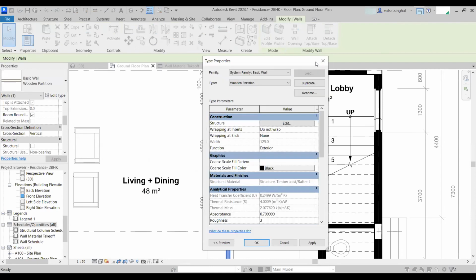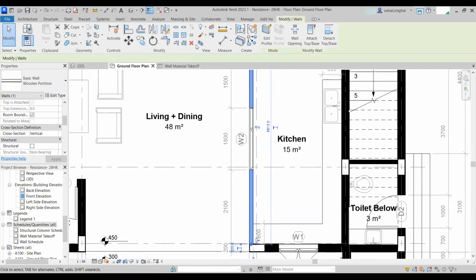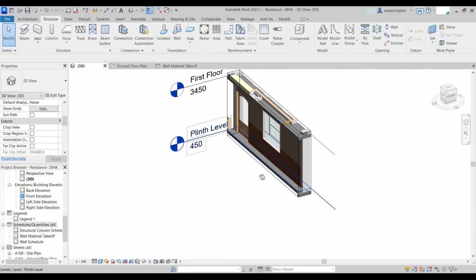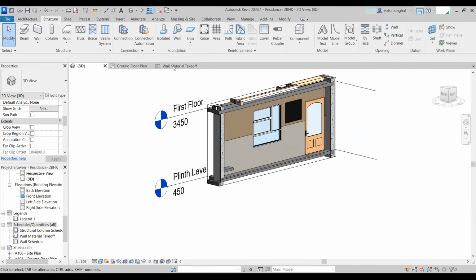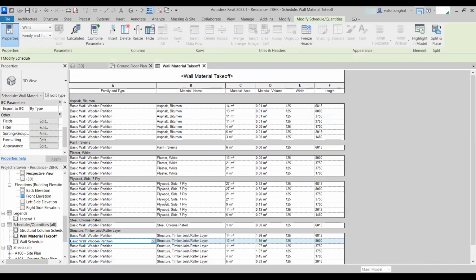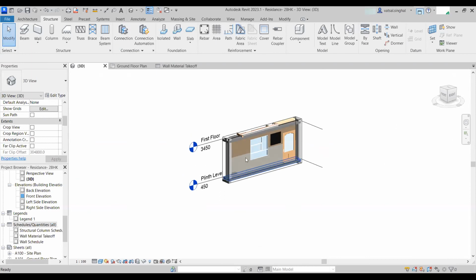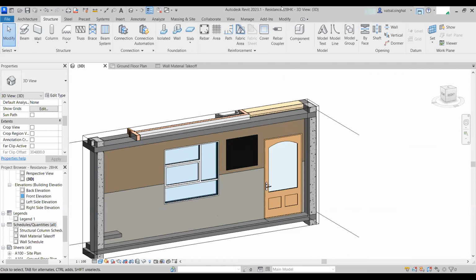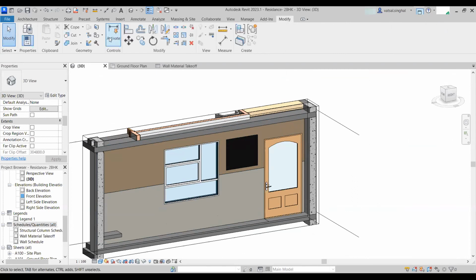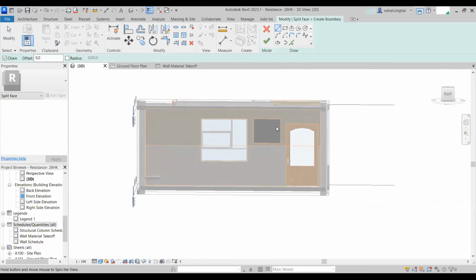The reason for this is since it has a property of paint applied over here. So if I go to, I'll isolate this option and I see here. So here there is this plaster paint that is available in this material takeoff, white material takeoff. So I go to 3D. So this is applied through the split face option here in the modify tab. So if I want to apply a different material again, you have this option over here, the split face option. You can just select a face and split it accordingly. So suppose I'll just show you how it's done.